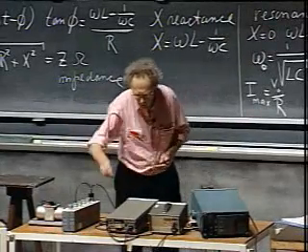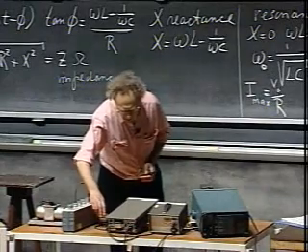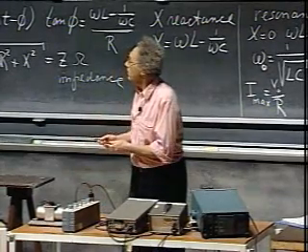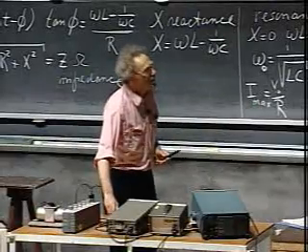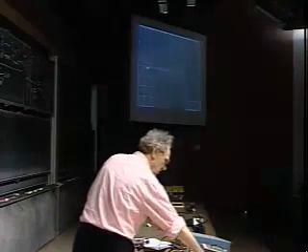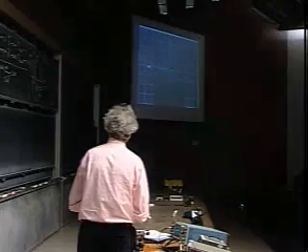And so I go now from 60 to 100. I don't double it. I can't go any further than 100. But you'll see a substantial reduction. So if you're ready for this, remember this height. And now you see 100 ohms, and it is much lower. It was this height before, and now it's only here. But notice the resonance frequency has not changed.